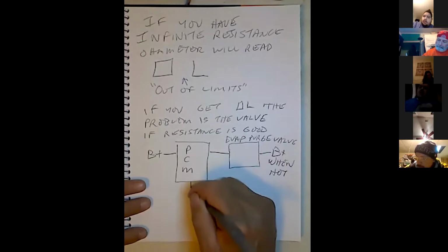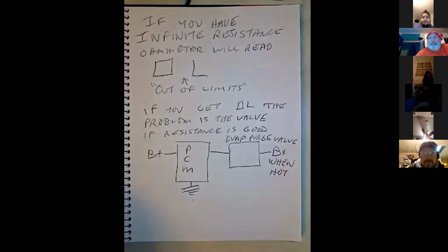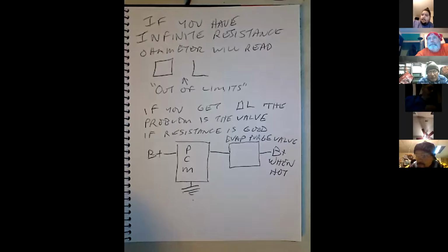That means ignition is on. Yep. And the PCM, I think it's ground side switched. I would expect it to be ground side switched, but it could be elsewise. Then what you have to do, my friends, what are you going to do, Chuck? Well, after you ohm it out, if it checks out, you check for voltage. If the voltage is there, my own feeling, I would probably run that smoke machine and see where that vacuum line goes to that solenoid, pump it full of smoke, and actually see if that valve is passing the smoke through. Yeah, but that's not going to cause a purge valve circuit open.